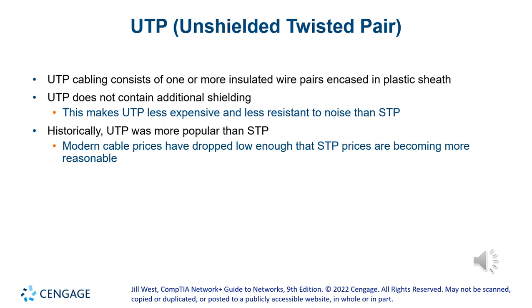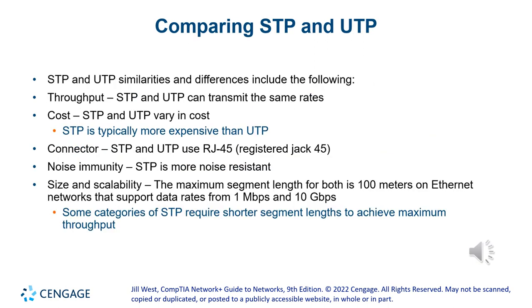So when you run those long cables, 90 meters or 80 meters, cables that are super long, or through the whole floor, that horizontal wiring, remember the horizontal wiring. When you run that cable in, you might want to run STP just to prevent any interference on the cable and make it more efficient, much better communication, and a more robust communication. And if the price point is not too much, then why not, right?